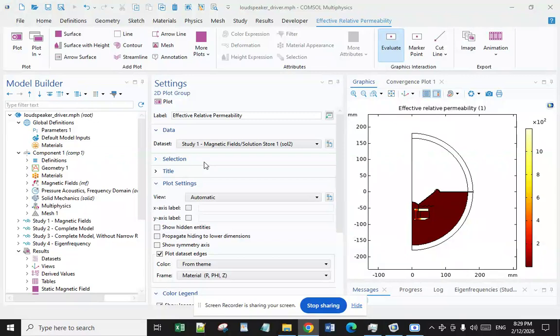Basic components. There are two basic components in an electromagnetic acoustic transducer. One is a magnet and the other is an electric coil. The magnet can be a permanent magnet or an electromagnet, which produces a static or quasi-static magnetic field. In electromagnetic acoustic transducer terminology, this field is called the bias magnetic field.